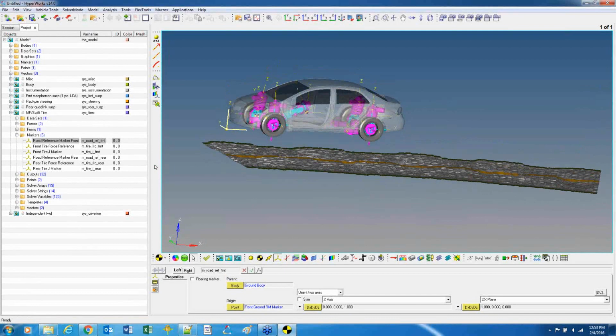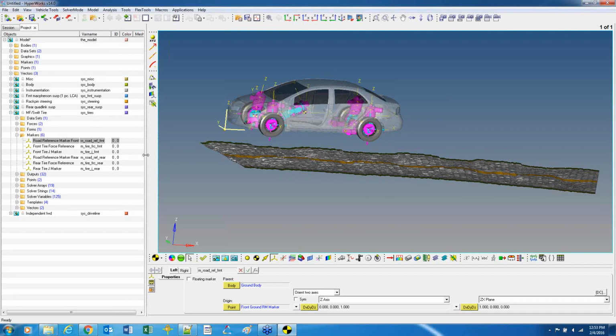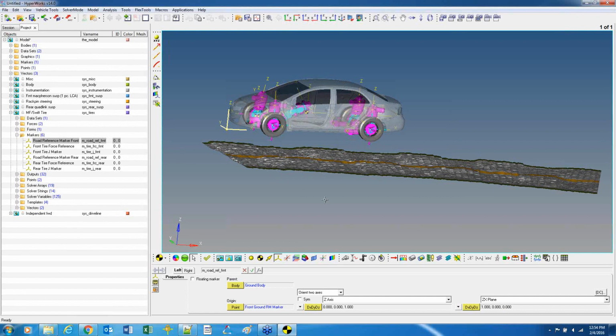Another question, Shari John. Is the RSP file also a road profile? Yeah, you can make the RSP. As far as whether the format's taken directly or whether you convert it, generally, it's straightforward to work with any kind of formats. So if you pick the RSP directly, I think that can be used directly, but if not, then HyperGraph reads an enormous amount of formats and saves to over 50 different formats. And we can use that often to convert from one format to another. But yeah, the RSPs, I believe, are supported fully.